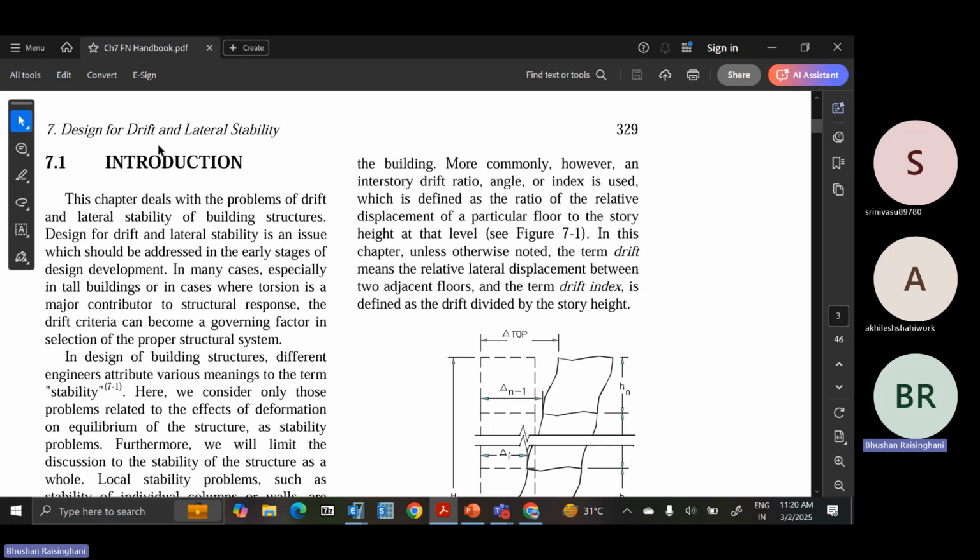Right. So that is the gravity load PCR, after which the column can become unstable either due to the application of a small lateral load or any increase in the axial force, which will lead to lateral displacement in the column. Due to the axial load also, the column may displace from its position in the lateral direction. So that is a small delta.